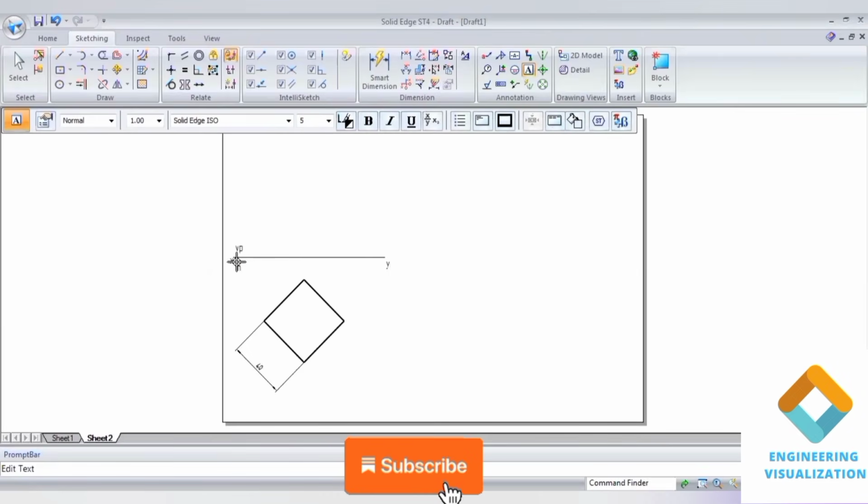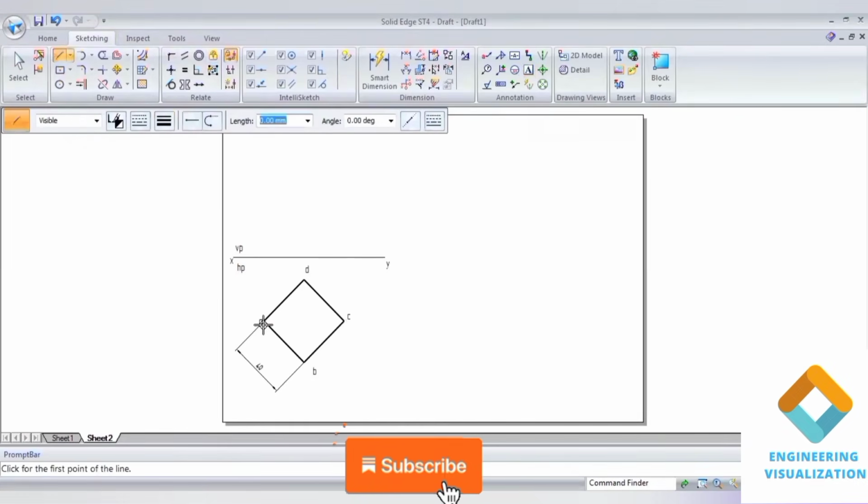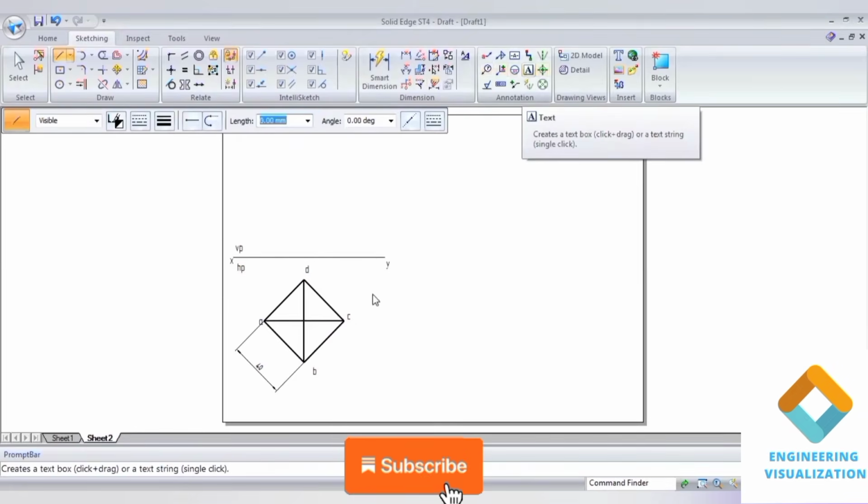Write XY, HP, VP, and draw the projection lines upward to construct the front view. So here the top view notations can be written ABCD. Since it is a pyramid, we need to draw the slant edges with thick lines. If it is a prism, it should be thin lines. So you all should know the difference. So thick lines we have drawn.